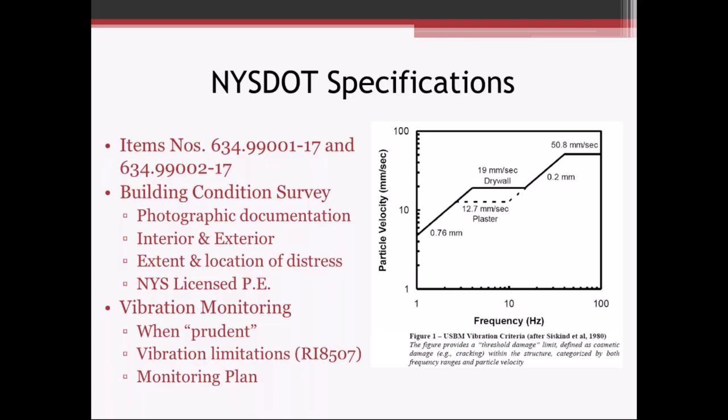The DOT specifications do require that the condition survey be performed by a New York State licensed PE. In the vibration monitoring portion of the specification, they state that vibration monitoring should be done when prudent. So obviously there's a little bit of a gray area there, right? It's kind of subjective. Typically, if they're referencing the specification, then they're going to require vibration monitoring to be done.